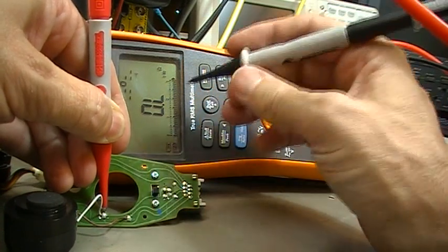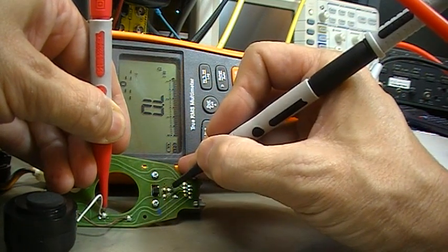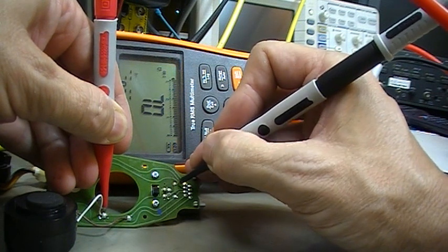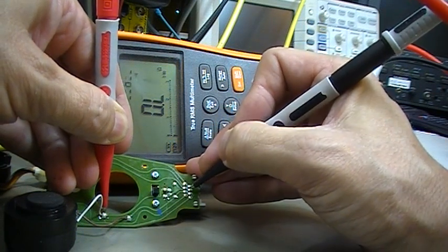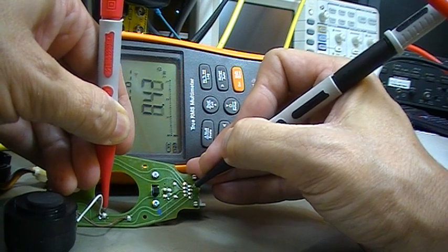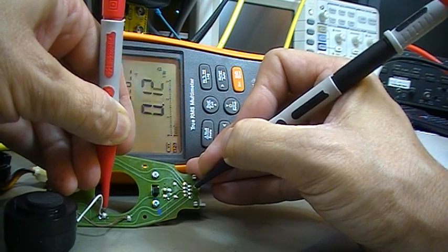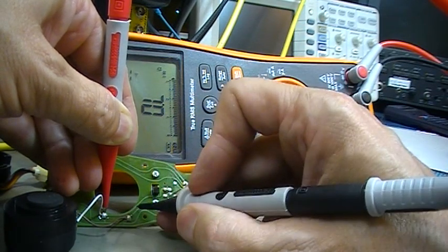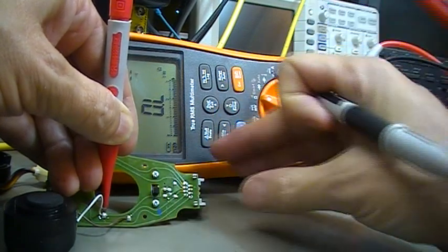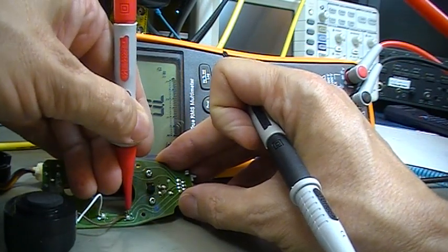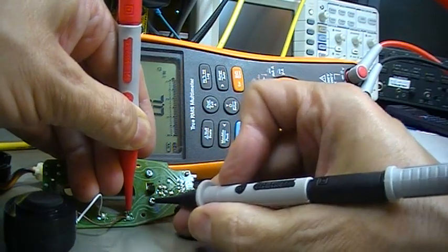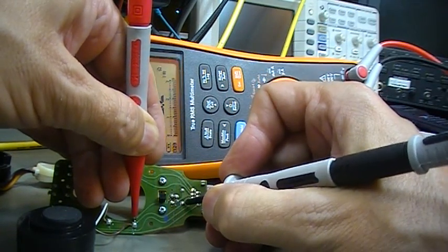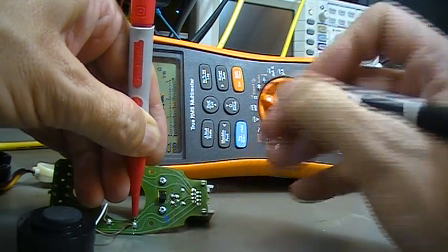So let's switch it to the little bridge, and now you can see in here it is already there, and it is available at this connector solder point. So therefore I would say mic plus seems to be okay. So let's do the same with mic ground, and ground will be here and there, so that is okay.